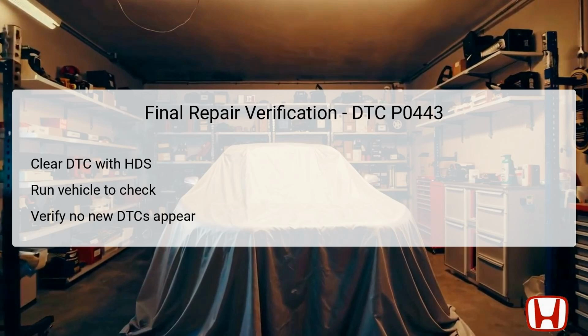Pay close attention to the dashboard for any check engine light indications. Upon completing a suitable driving cycle, return to the HDS to check for the absence of any new or pending DTCs. This final verification step reinforces the reliability of your repairs and ensures that the EVAP system is back to operating as designed.